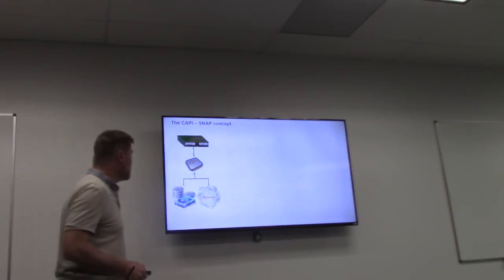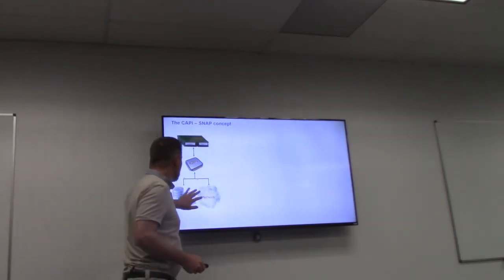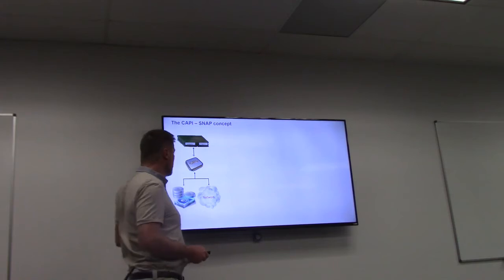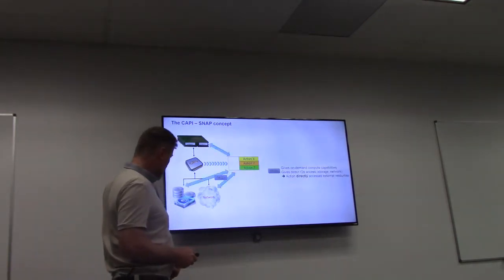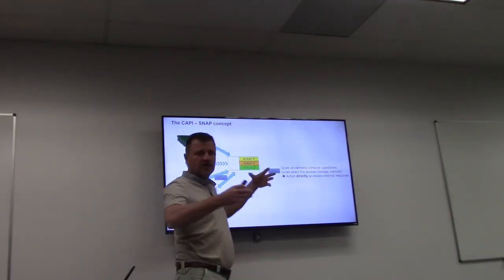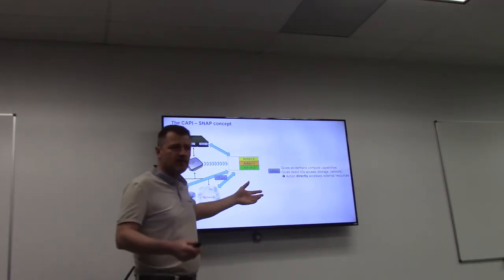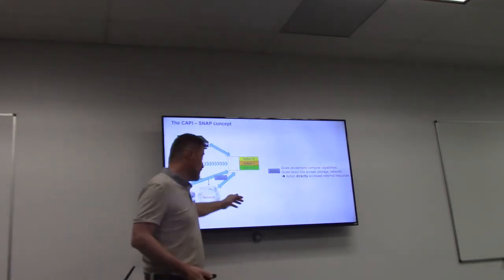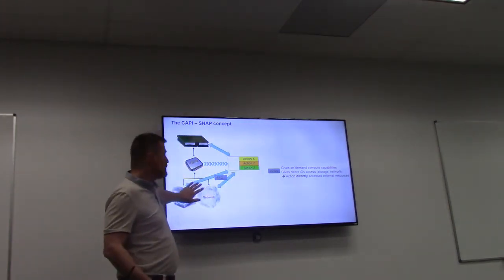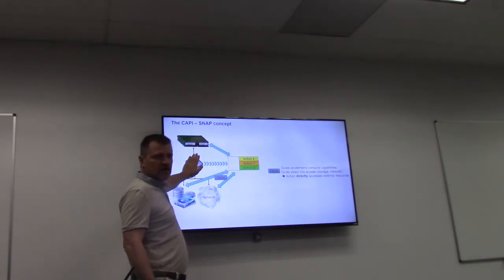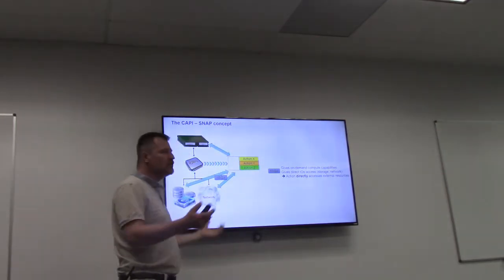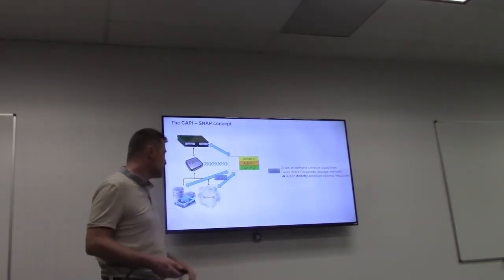The SNAP and CAPI concept is the following. We have external IOs, which are today connected to a regular CPU, connected to its host memory. If we introduce an FPGA, we can have several actions. Today the SNAP is supporting one action, but the architecture is aimed at supporting several actions should there be a need. And it's open source, so you can also develop yourself. The FPGA can have access directly to these IOs, so there is no need for the CPU to be using time to access that. You can go through the FPGA. So the FPGA is providing a new I/O access to the processor.